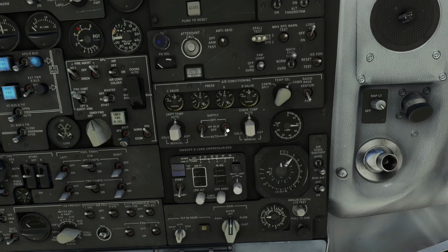This will close one of the bleed air valves off the engine. If you need extra power, you basically reduce some of the efficiency and power to your packs, but still have some and get yourself some engine power back. So if it's really a hot day or you need a lot of engine performance, instead of being in auto, you can go into HP bleed off, and you basically reduce some of the power your packs get because you're reducing some of the bleed air you're getting off your system. And then obviously off is closing the bleed valves off the engines altogether and turning your air conditioners off as well. So that is your air conditioning system.